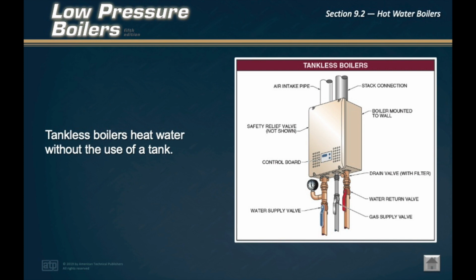When there is a demand for hot water, the water temperature sensor of a tankless boiler measures the water temperature and starts the heating process. The temperature sensor sends a signal to the control board. Depending on the calculated return and desired water temperatures, the gas flow or electric current into the burner assembly is modulated, and the electronic ignition sequence begins. Water is heated to the desired temperature as it circulates through the copper heat exchanger. When the temperature in the building space is adequate, the tankless boiler shuts down and remains in standby mode, pending the next call for heat.